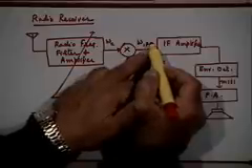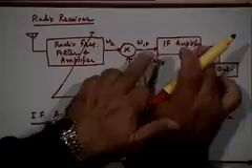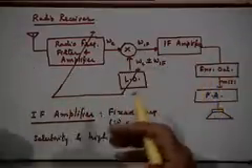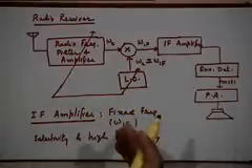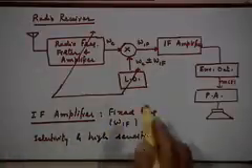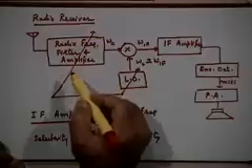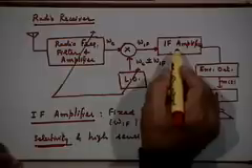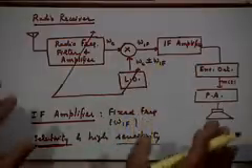So these will also be present here, but this IF amplifier will be able to reject them, because it is designed to only accept the true omega if, right. Any other close by frequencies which are not of interest, it will be able to reject them. You can make it frequency selective enough to reject all close by signals which are not rejected by the RF front end. That is what is meant by selectivity. I can make it highly selective, and highly sensitive by providing a large gain to it. Okay, so this is roughly the block diagram of a radio receiver.